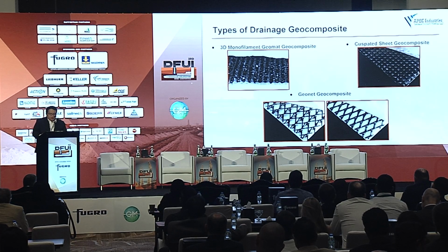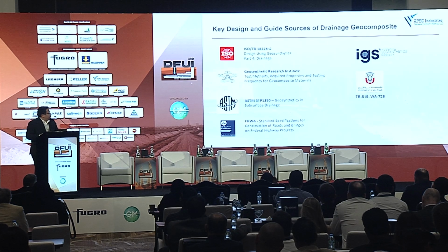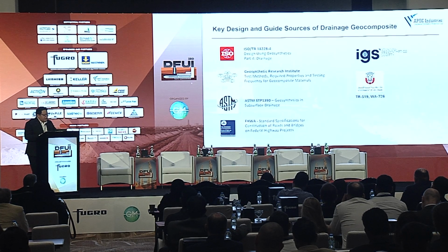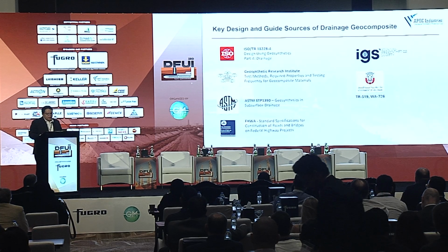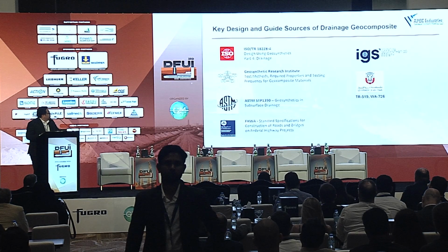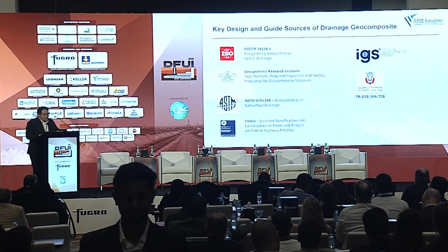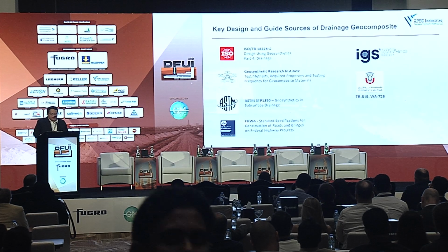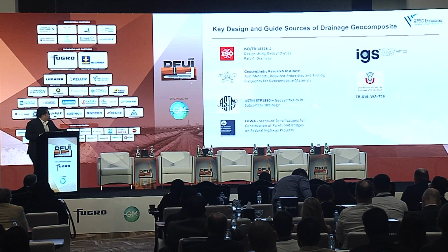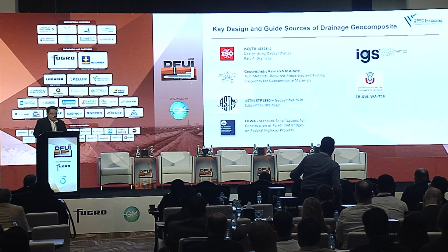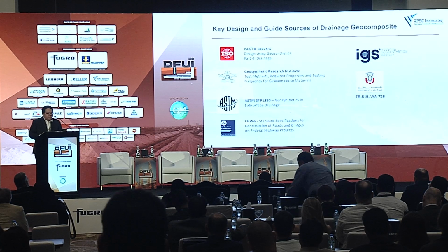So the design of drainage geocomposites is supported by several international references. This includes ISO Technical Report 18228-4, which covers the design of geocomposites for drainage application, Geosynthetic Research Institute publications, ASTM STP 1390, the FHWA guidelines, and also International Geosynthetic Society publications.